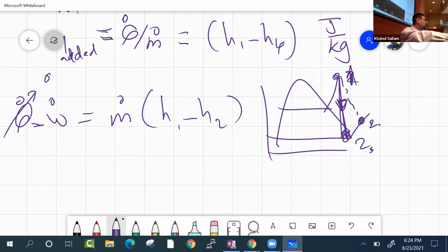Why is it so hot? But the fact that you managed to put your hand on a 1,000 degrees Fahrenheit turbine and you didn't burn your hand tells you that the adiabatic assumption is not really that bad. Maybe it's 40 or 80 degrees outside, but it's 1,000 inside. So it's okay to assume adiabatic.